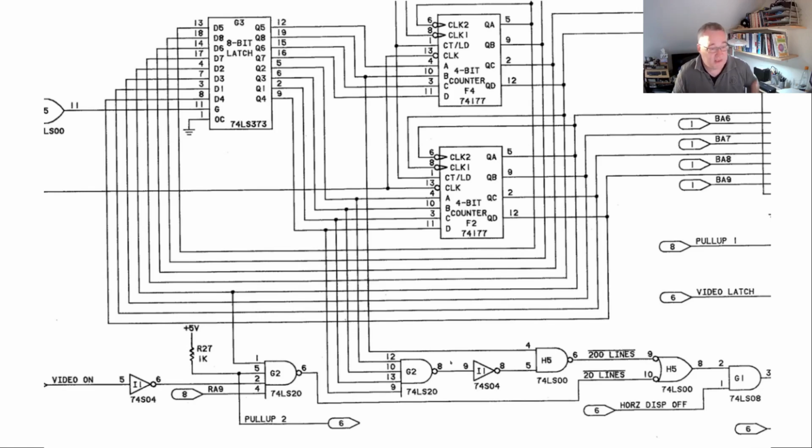So how do we compare the value of the counter or the hold register with 250, which would be the start of the raster line after the displayed character? So basically the overflow into the not seen, into the bottom blank.